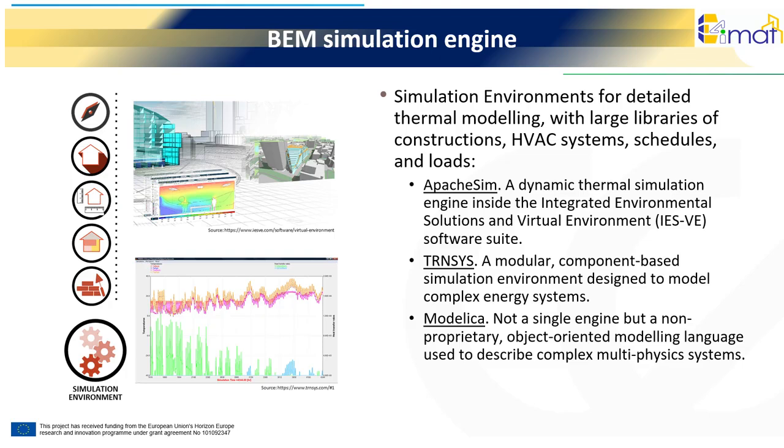Modelica, not a single engine but a non-proprietary, object-oriented modeling language used to describe complex multiphysics systems, like thermal, electrical, mechanical, or control systems. It provides an equation-based modeling of the building for digital twins and advanced control development.